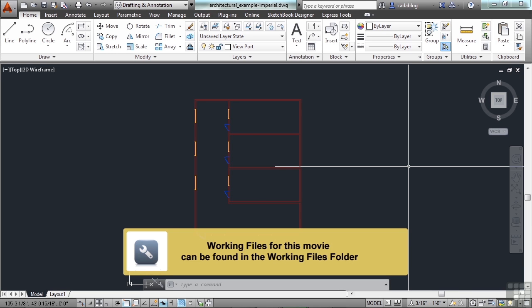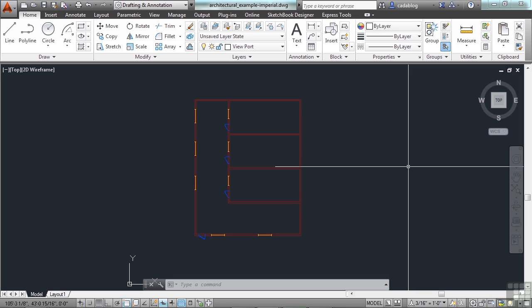You can make drawing layers invisible either by turning them off or by freezing them. We've briefly mentioned them in the last few sections, but I want to take a better look at them so you can better understand when you want to thaw something or when you want to turn it off. Turning off or freezing layers is a very useful thing to do if you need an unobstructed view when working in detail on a particular layer or set of layers, or if you don't want to plot out details such as reference lines or other things like that.